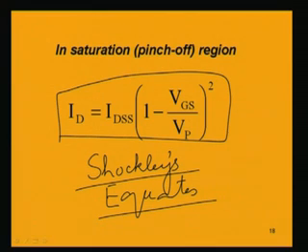So, it will be whether VGS negative or positive, and we have seen that we generally will be having only negative voltage, because VGS is always given a negative voltage, and pinch off voltage also has to be a negative voltage. So, the current equation can be used for finding out another important parameter, which is the transconductance gm.